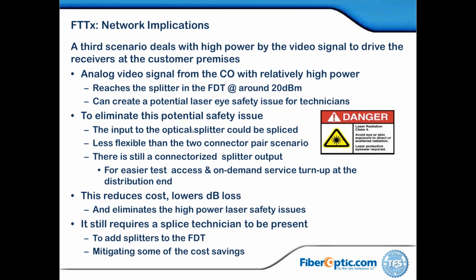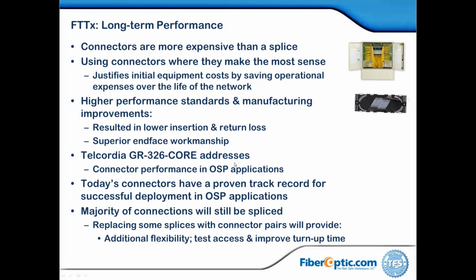So you can see where the plug-and-play becomes more popular today than the other tool. So connectors are more expensive to splice. They add additional losses, which normally you think would be a big deal. But higher performance and manufacturing means that using today's pre-connectorized assemblies, very low back reflection, APC polished types of connectors, and in the class we go into much more detail, that today they have a proven track record and it's very common.